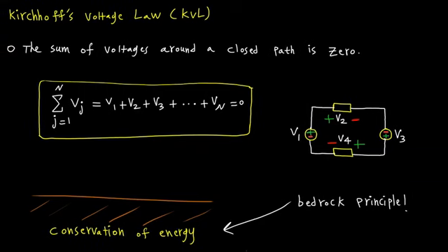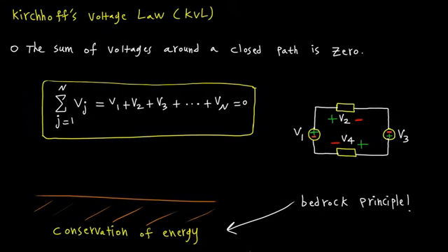with your sign. This is a point that I'm going to repeatedly reiterate, because it leads to so many errors when you first learn it. If you're careful with it, you can save yourself a lot of trouble and just do the problems correctly from the get-go. So as long as you stay consistent with the signs that you assign to these quantities, you should be good to go, and the correct polarity of voltage or the correct direction of current will sort of pop out of the equation, and I'll demonstrate that clearly in examples to come. So in this case, as we stated, that's what the law says here. KVL is based on conservation of energy.